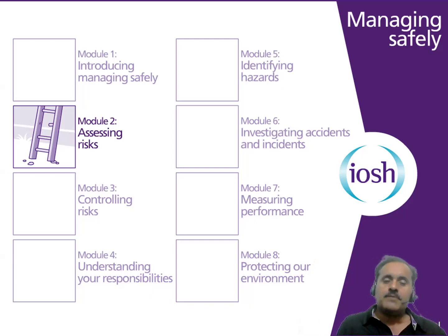So once the people are assessed, the second area of interest will be the equipment. Is there proper inspection and maintenance of the equipment, is a proper logbook maintained, is there a safe distance between machine and machine, and furthermore, are machines properly guarded? Do workers have the education to operate the machine safely? Are there proper emergency buttons displayed in red color?